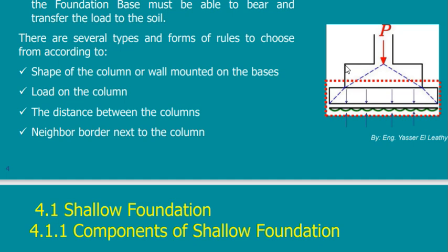And then I get the new area. In this case, the new area will give you a stress that is less than the allowable of the concrete. But this is the maximum you can take because I cannot extend my plain concrete outside of my reinforced concrete.